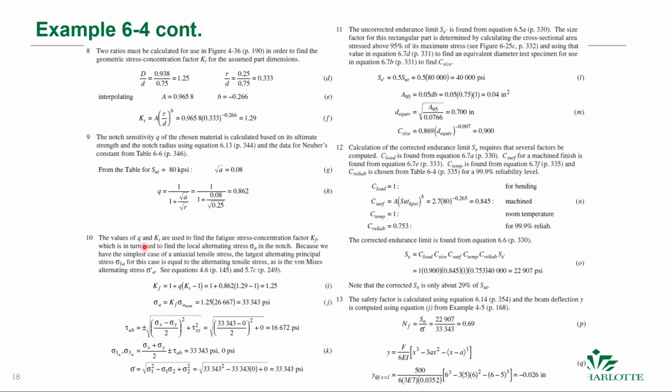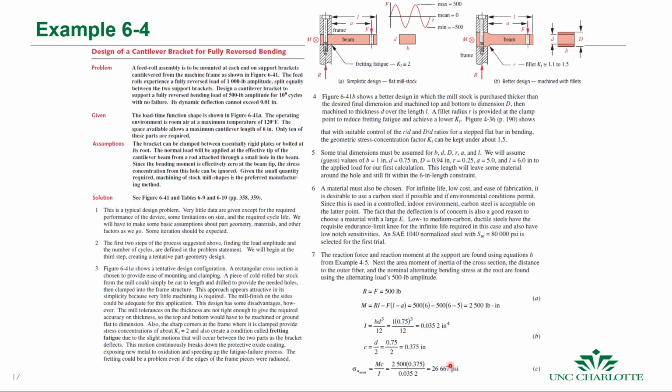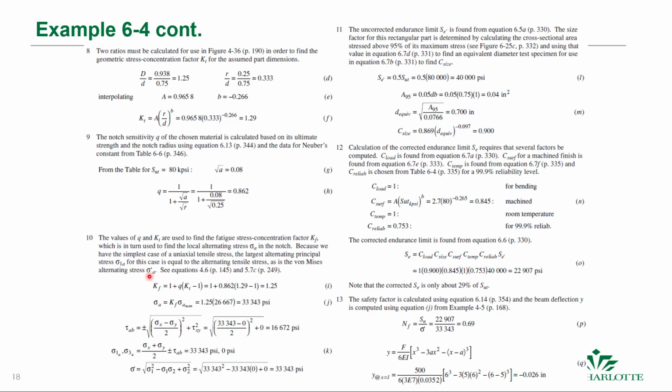Okay, so then what we can do is get the calculated fatigue stress concentration factor. Okay, and in this case, it's larger than 1, but it's less than Kt. So we use Kt here for the static case to make sure that we don't have static failure, and then in this case we're calculating Kf to make sure that we don't have a fatigue problem either. Okay, so then we can calculate our